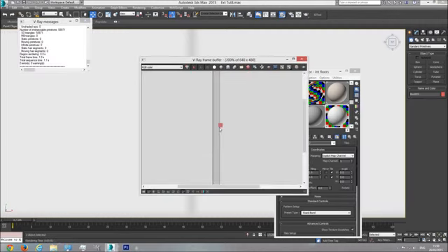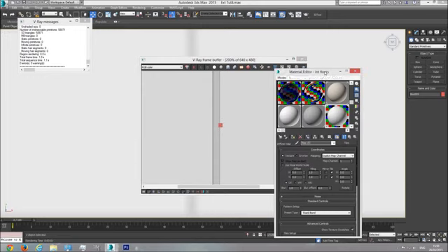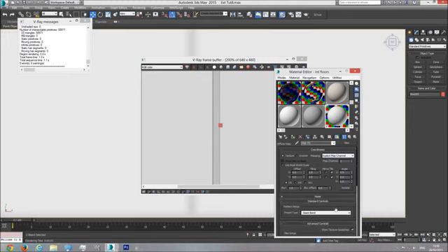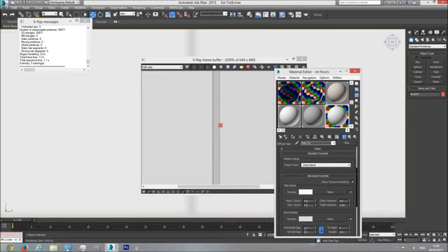As you can see, this is shorter than this, so this is too long. I'm going to go back to my material, into tiles, and make the separation not 0.1, but 0.08. Once I change this, this changed automatically. So this is vertically and horizontally. You have horizontal and vertical, and it is locked to be the same.